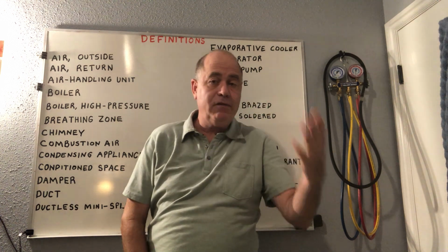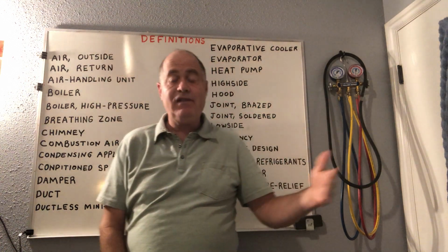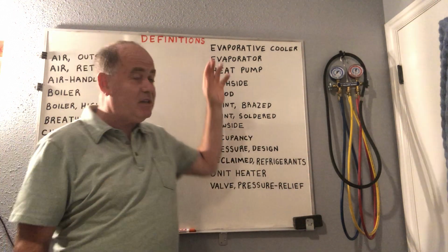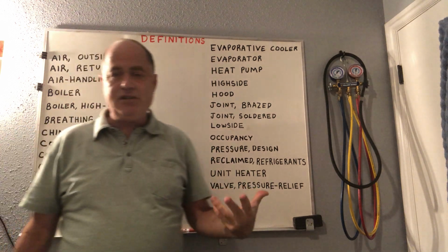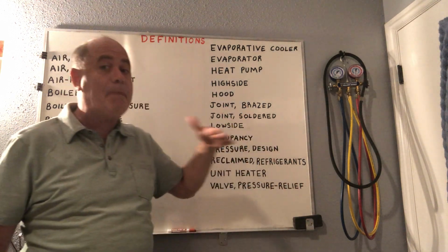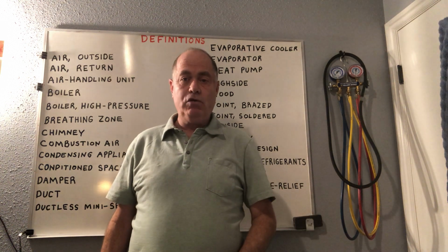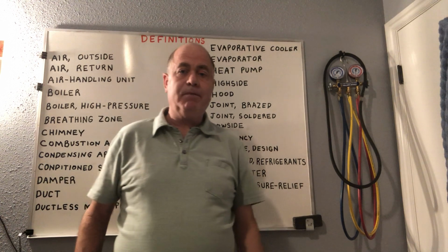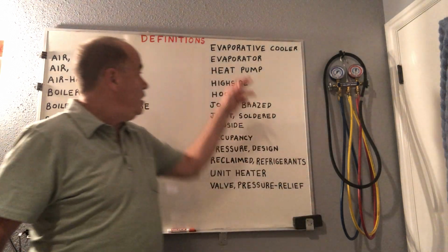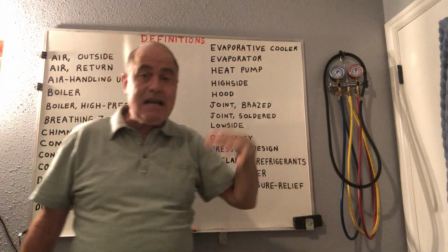You can get a lot of water that can evaporate into the air, and you can get a lot of inexpensive cooling. I've done some experiments with it. If it's dry enough outside, like 10% relative humidity or whatever, you can drop the temperature like 13 degrees going through an evaporative cooler. Okay? If it's almost raining outside, all you're going to do is move the air. That's it.